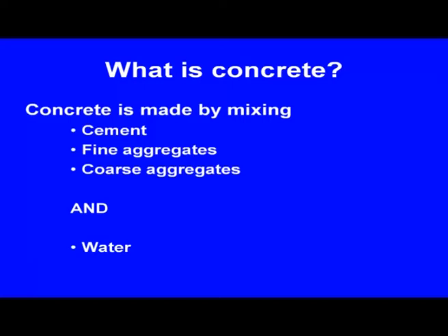If you add more water, then you have problems achieving the strength. If the water drains out of the casting, you will find voids, and we call it honeycomb. If there is too little water, all the material will not be wet and you will not get the required strength. Just to give you a demonstration, we have coarse aggregates, cement, and water, in proportion, the water to cement ratio.